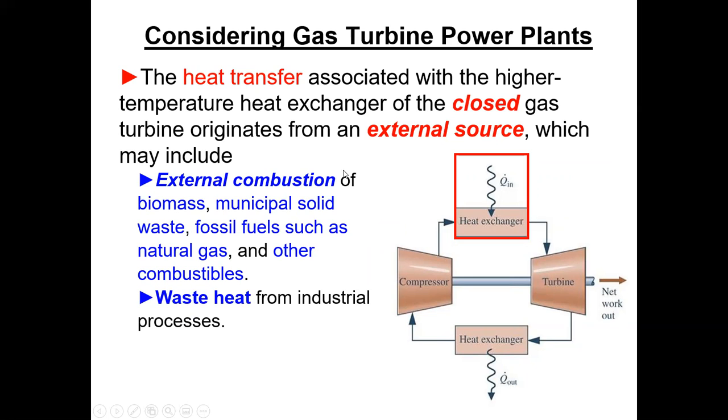Waste heat. You could have waste heat from, even though the waste heat system that I've discussed here, I don't see many of them, is the organic Rankine cycle, which is the basic Rankine cycle with the refrigerants or the organic working fluids that boil at such lower temperatures. Because not that many industrial applications have high enough temperature waste heat to really generate a lot of steam. There's a few, but most not so much.